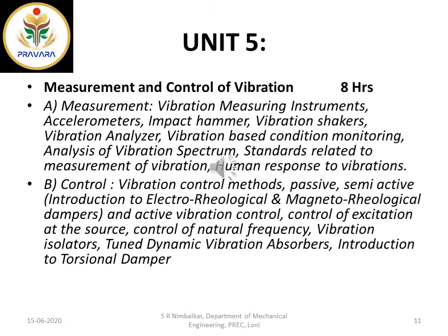Then there is a vibration analyzer. This vibration analyzer is basically a vibration meter, and it measures the vibration. It is one kind of electronic device able to process the vibration signals. Whatever the vibration parameters, this device is able to process the voltage signal and display the vibration value, such as acceleration and velocity.